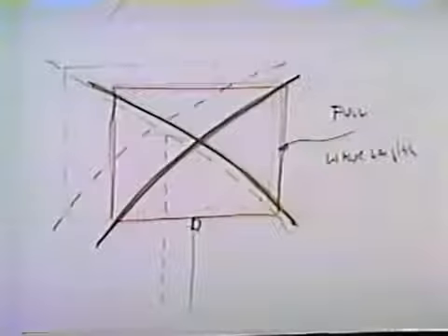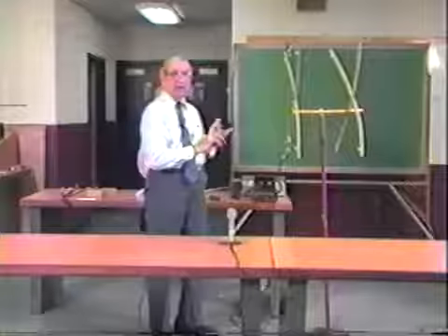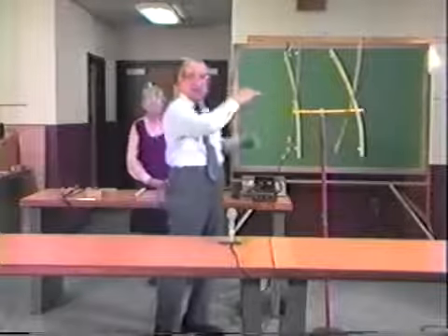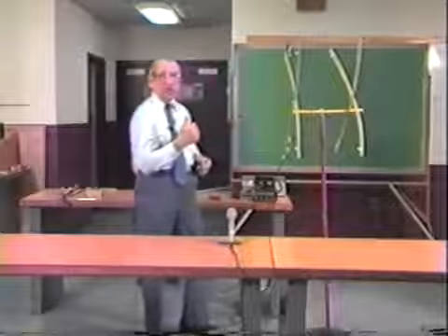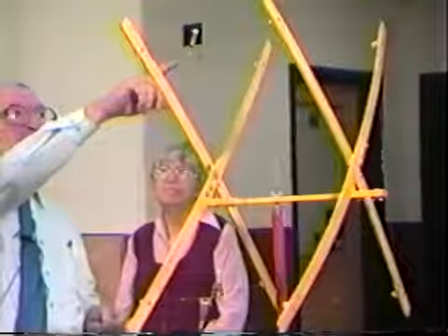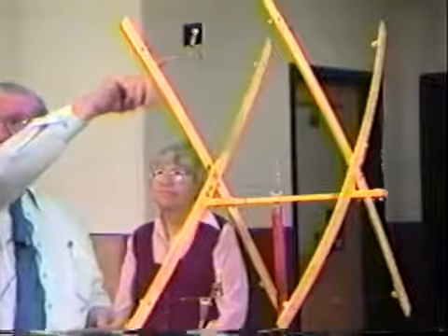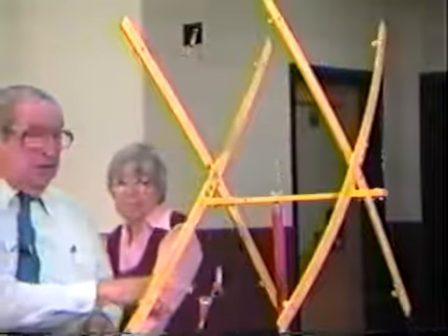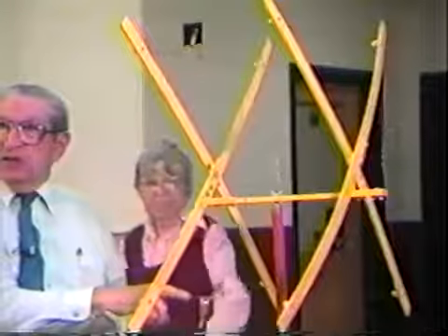Being full wavelength long now, we can discuss it in two ways. We can either say this is a full wavelength, or we can consider it as two half wavelengths. Now we're going to discuss it as two half wavelengths for a very obvious reason. If you notice, we have a current loop at this top portion, and we have a current loop at this bottom portion. The bottom portion, of course, is the portion right by the termination.